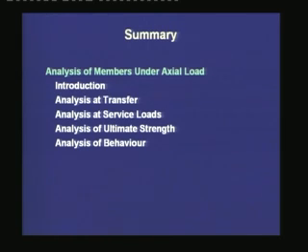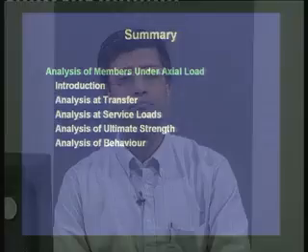We may have piles which may be under axial compression or axial tension, but usually piles are also subjected to moments and shear. But the whole purpose of studying the behavior of members under axial load is to understand the difference between prestressed members and reinforced concrete members, and it gives us a foundation to understand the analysis procedure for members under flexure.